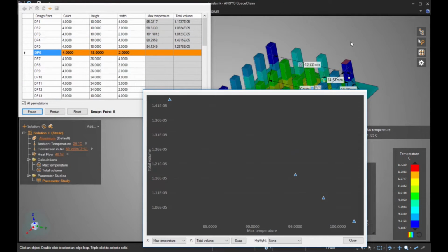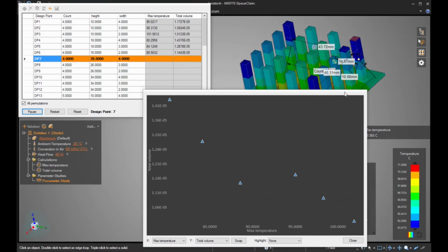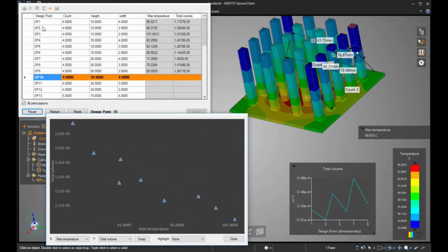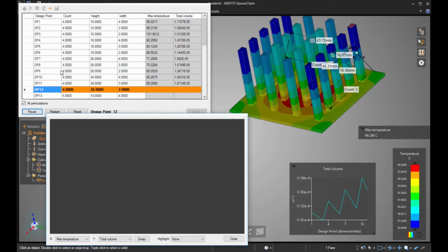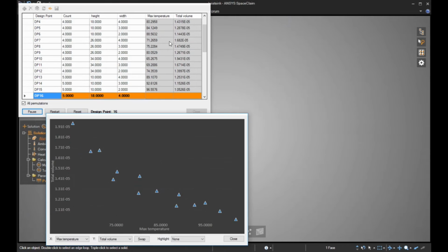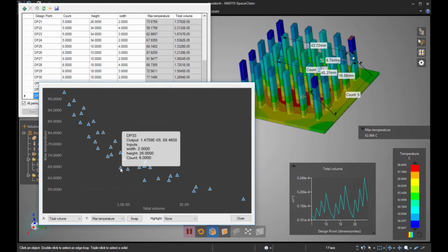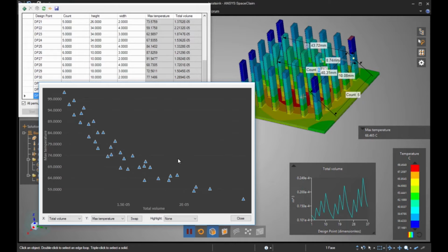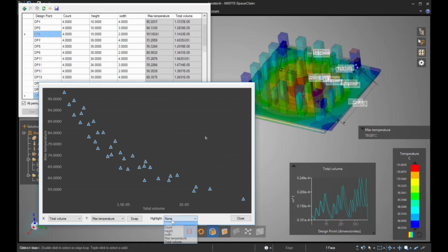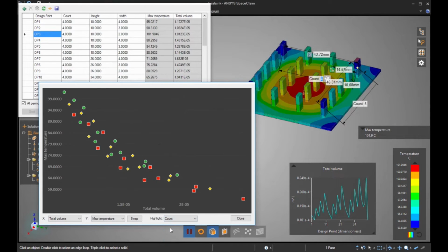As the calculating continues and more data populates the chart, trends begin to emerge. Discovery Live, by default, plots the design goals instead of the geometric or physics inputs. This naturally forms a Pareto frontier, letting you quickly see which iterations are better than others. The interactive chart in Discovery Live means clicking a design point will toggle to the 3D model and show the simulation results. Data in these parametric sweeps is easily configurable, so you can observe various trends and parameters and concretely tell you which variables have the most impact on your design goals.